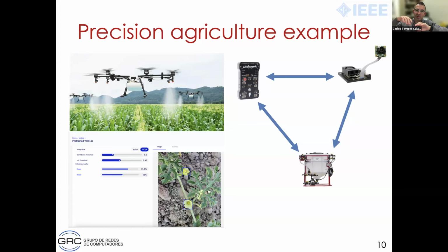And then our protocols rely on the UAVs talking to each other, and based on their conversation, we can decide to change trajectory. So that's when we give different orders to the flight controller via the telemetry port. But the intelligence is running on another embedded system like Raspberry Pi or Jetson or whatever you want to run. And we are building our own software using standard TCP/IP protocol stack, a generic application level solution with Java,